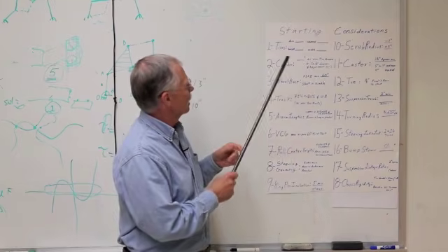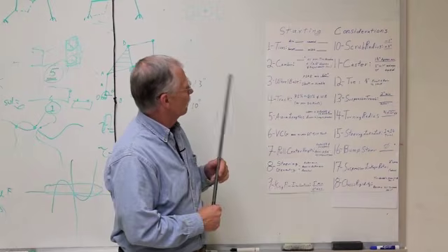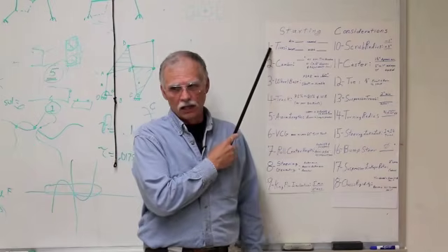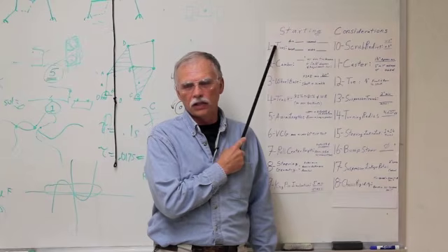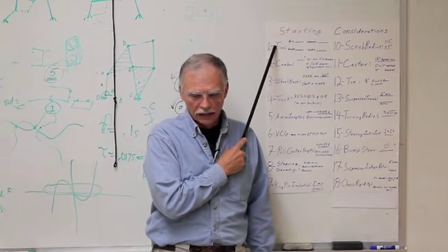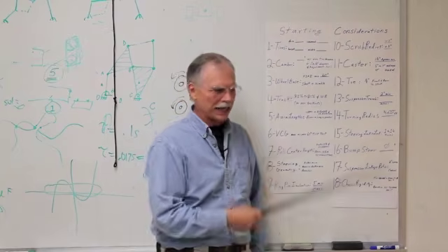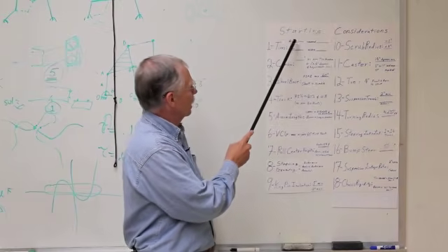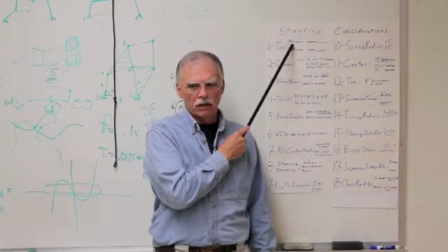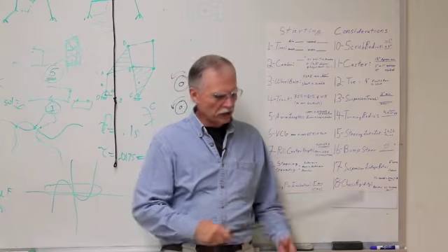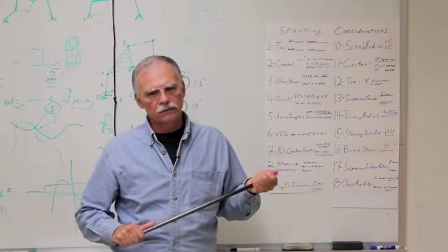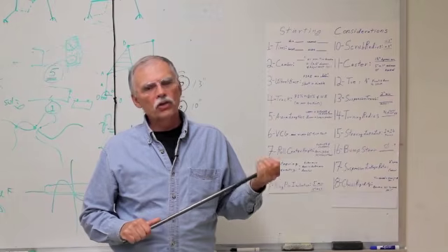All right, now your contact patch and dealing with it and optimizing it means you're dealing with tires. So the first thing you deal with is select your tire you'll be using. Don't think about engine, don't think about anything else. Think about the tire you're going to be using. And the most important initial thing is the tire diameter. Now in FSAE you can use a tire as small as 8 inches in diameter. That's larger than a go-kart.